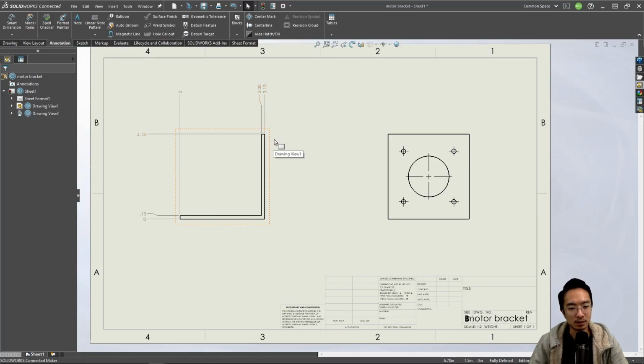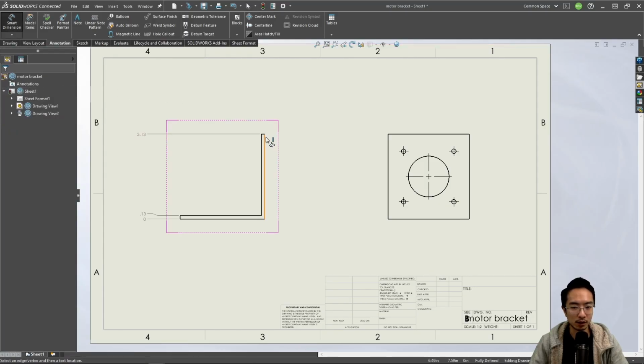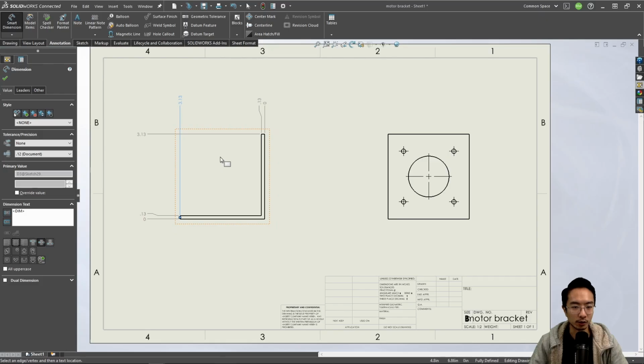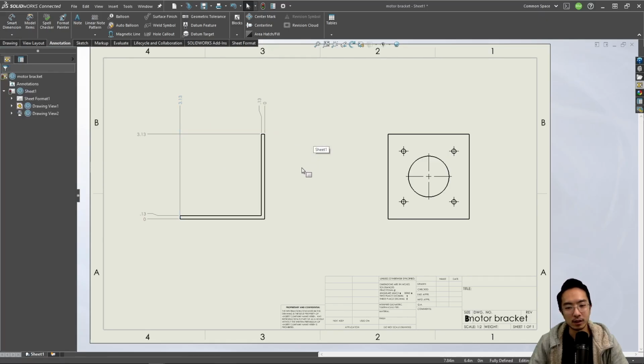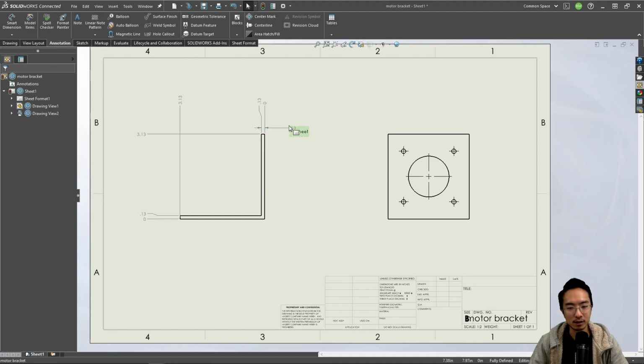And sometimes maybe you would start the 0 on the other end if it makes more sense to you. That way you can see the thickness more easily. So that's kind of a preference, if you think about where the 0 is located for the person. And sometimes you might see a smart dimension and just come in here and say the thickness. But in this case, that would be duplicate. So really, this should suffice to fully define this.